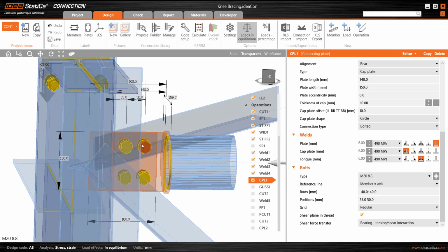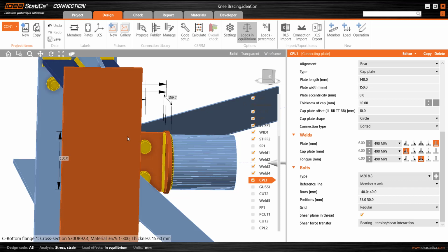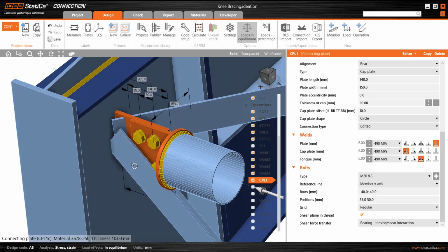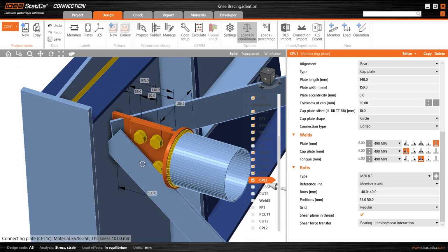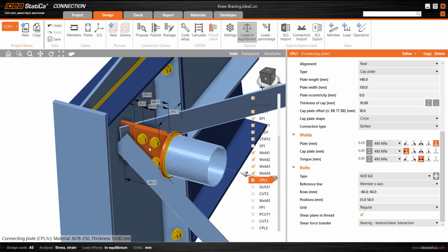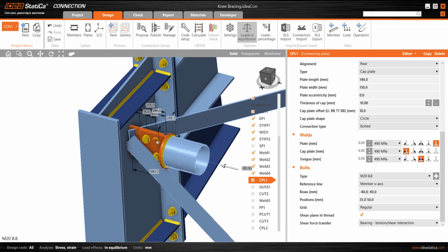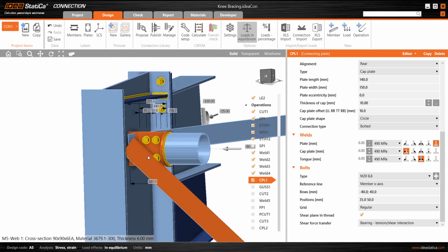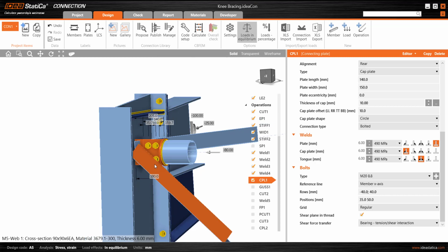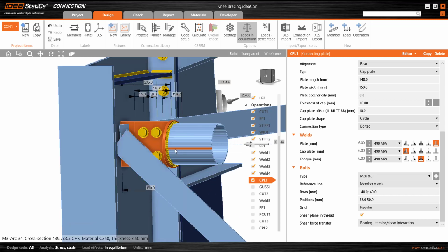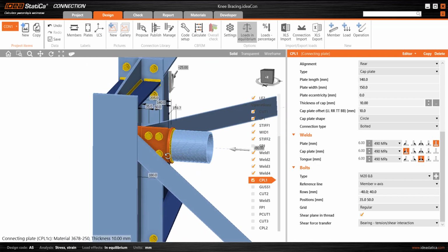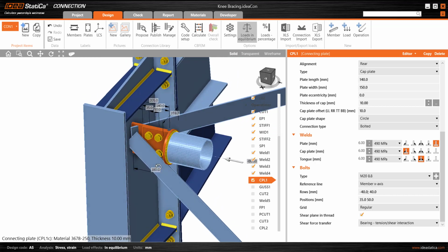I've got 4 bolts instead of just 2 because I've pushed this out a little bit further from the web of the column than perhaps the minimum would suggest, and that's to allow a little bit simpler erection in between the columns, a bit less springing required, and also I want to create a little bit more clearance for the bolts to the other bracing members and so on. So again, some trade-offs, some details to determine as you're working through the design, of course.